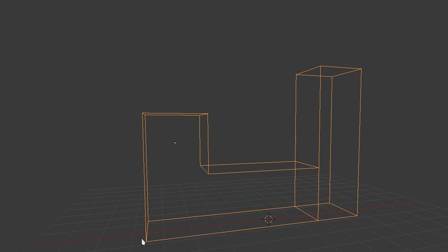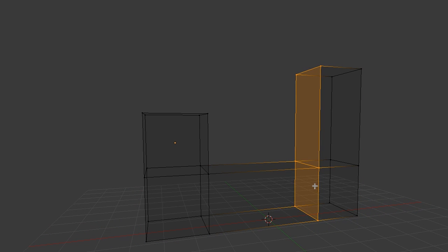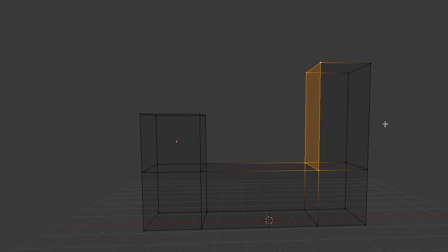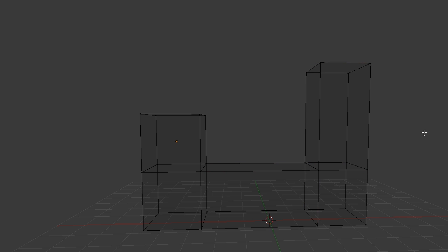We can go ahead and repair this by going into edit mode. I'm going to delete that face by hitting X and hitting delete, and we'll go ahead and fix the offending face. Now, here's one thing to note. Remember in our earlier lesson we talked about normals and which way the face is actually facing, whether it's facing in or out. You are not going to get errors in your slicing application if that's the case. It's going to trust that your normals are exactly how you want them, and it's going to slice appropriately. Always remember to check your normals.